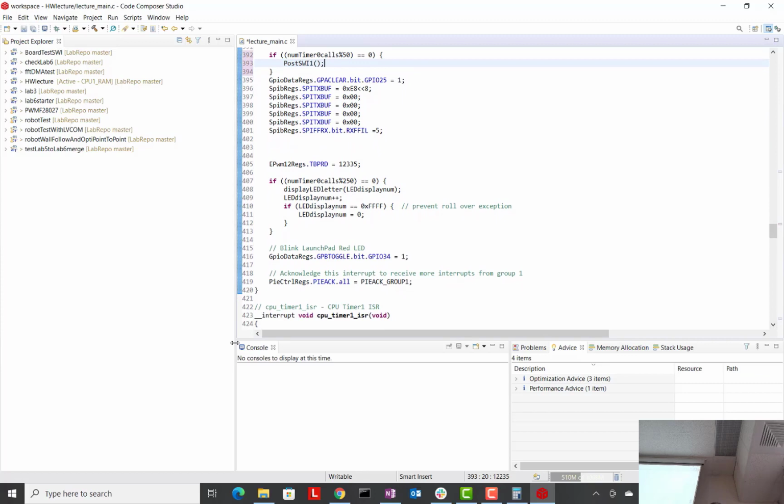So it'll do all this stuff and then exit out of CPU timer 0. Now that it's exited CPU timer 0, that means interrupts are enabled again. It's possible your software interrupt function could be called at that moment. But what if there's another interrupt with higher priority? That higher priority interrupt's going to get called at that time and run through its code, and when it exits, maybe then your software interrupt function could be called. Okay? Does that help a little bit with posting?